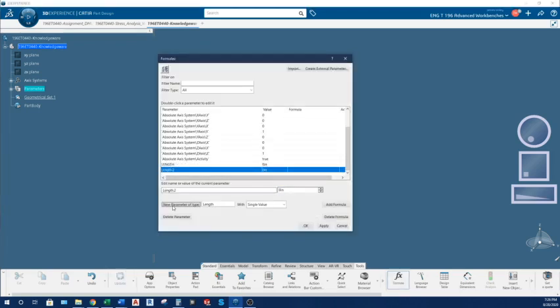We'll make another new parameter. We'll name this one WIDTH, all capital. Make sure we put our value in there. If you don't put those values in there, once you make that link, your model is going to act up on you. So it's easier just to put any value you can in there and not leave it at 0.